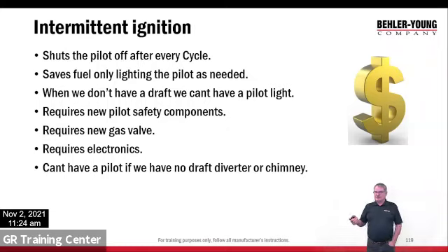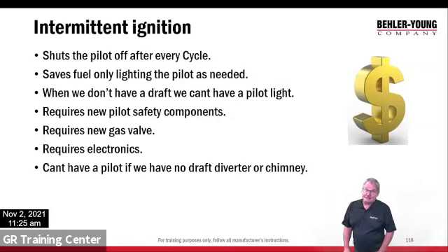When we got rid of the draft, remember the big chimneys? We had a draft. When we got rid of those, we can't have a standing pilot anymore because there's no vent anymore, right? There's no draft. So we had to come up with new pilot safety components. We had to come up with a way to light the pilot. We had to come up with a new style gas valve. Thankfully, electronics came along.